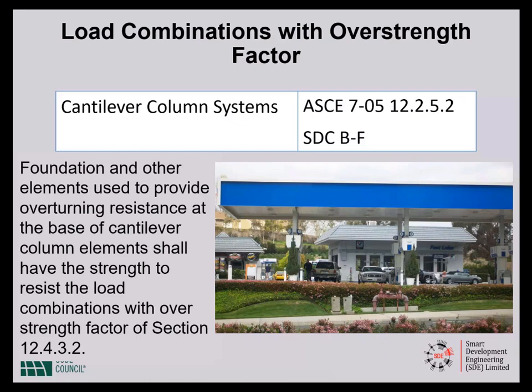They are not to be used indiscriminately everywhere, wherever you feel like using them. They must be used where required by ASCE 7. They must not be used when not required by ASCE 7. The second part is as important as the first part. In seismic design, more is not necessarily better.